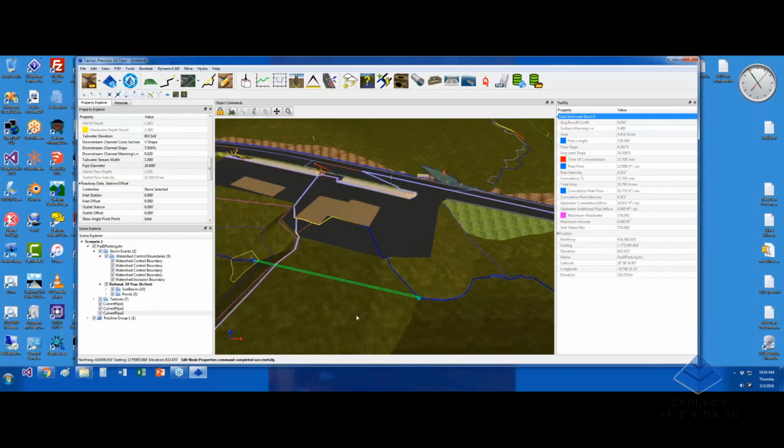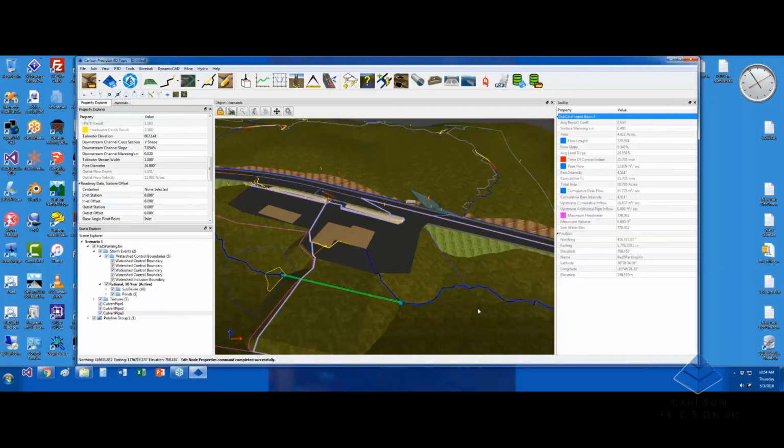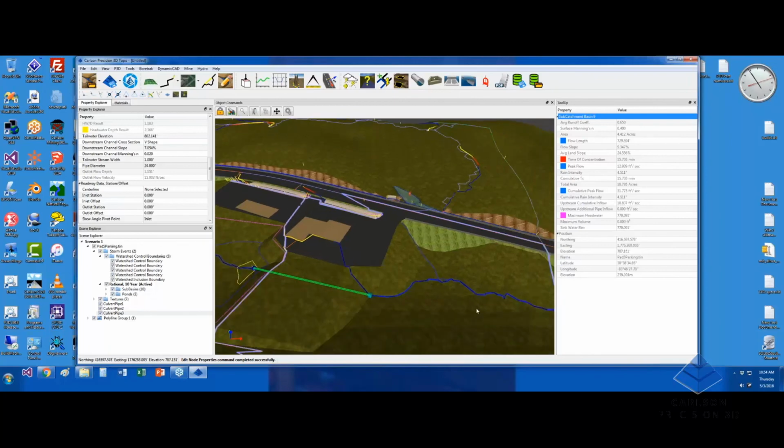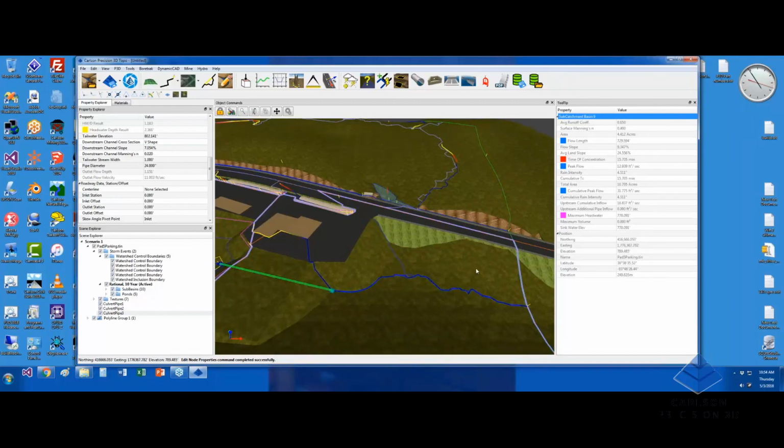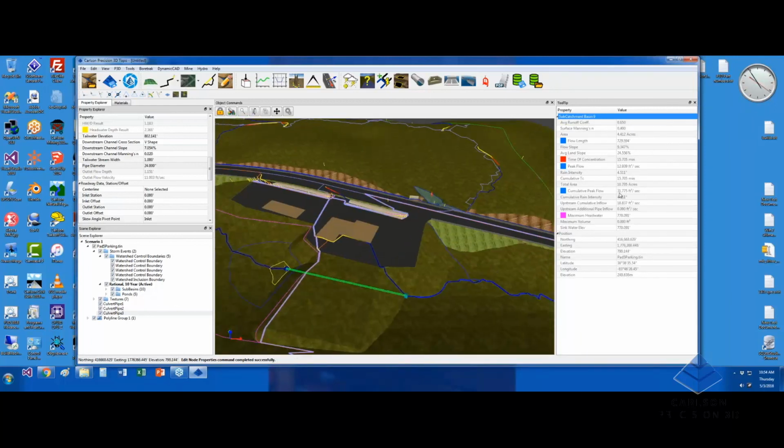And if we come back down into this subbasin 9, remember it's catching all the water from all these culverts so far. And you'll notice that we're up to a cumulative flow of now 31.7 CFS.